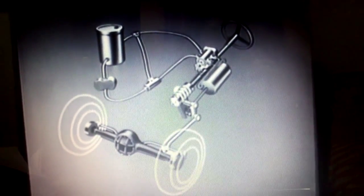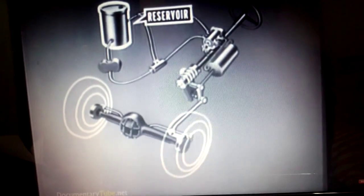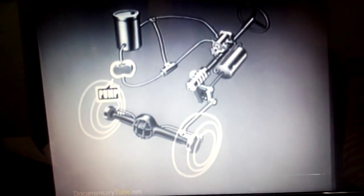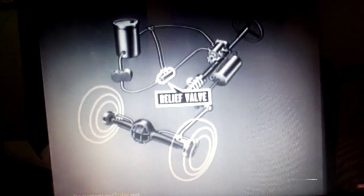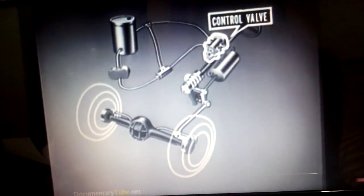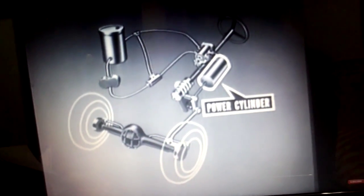Now to make it a power steering, we attach a hydraulic unit to it. As you can see, this is a hydraulic attachment. This eases the steering and makes the effort less. Now the fluid is stored here in the reservoir. It then moves to the pump, and the next part is the relief valve. It then moves to the control valve, which controls the flow of fluid into the power cylinder or back from it. This is the basic structure of a hydraulic assisted power steering.